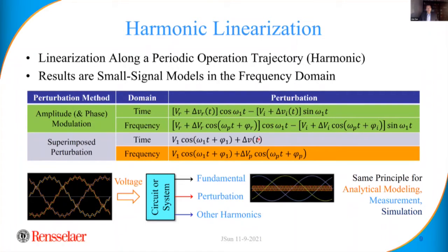If we directly superimpose the perturbation as an arbitrary function of time, this is where we run into this linear time periodic model challenge, right? So the method we apply is to introduce a perturbation in a sinusoidal form at a different frequency. So now your operation has the fundamental as well as a perturbation.